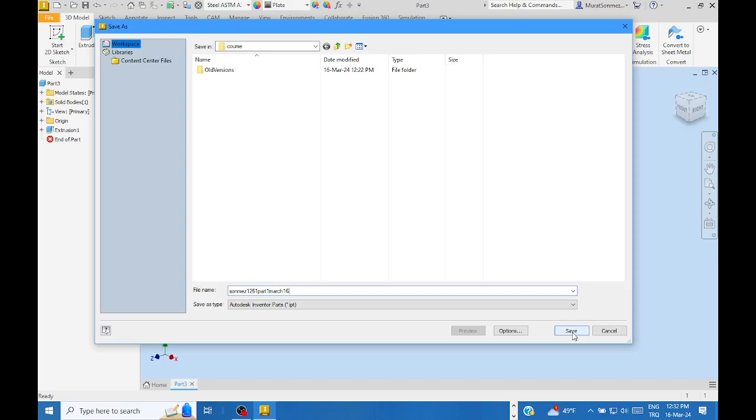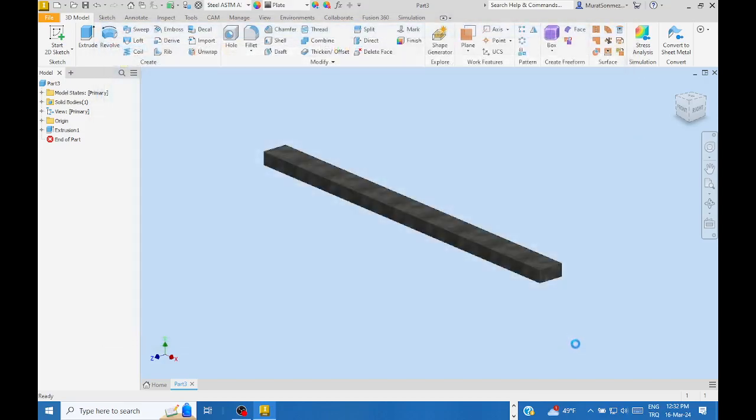Dear students, whatever the file name is in which we have the solid model, when we perform the stress analysis calculation and save the file one more time, Inventor in the background will automatically create a folder, and the name of the folder will be exactly the same as that of the solid model file. Within that folder, you can find the log files in which Inventor keeps the results of the calculations. After the saving, just have a look at the project folder.